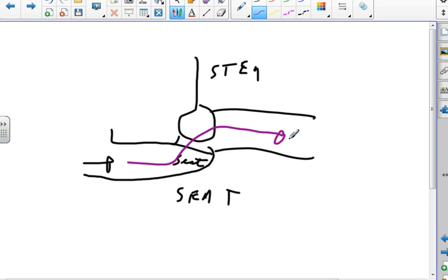Now, someone made a mistake and told you as an electrician to check whether or not the valve is open. Okay, the boss told you to go do that. Go check to see if the valve's open, and you happen to find the right valve. How are you going to know whether or not it's open? You check a valve open by shutting it.